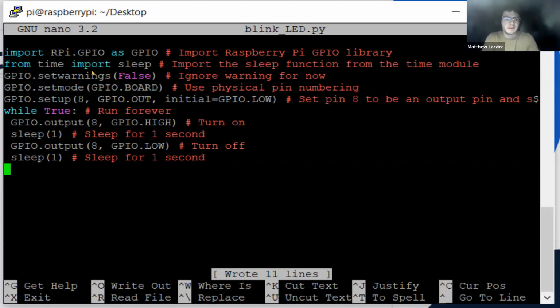But anyway, what I'm doing here is I'm importing the actual package that allows me to work with the GPIO pins. I want the sleep function because I want there to be a break between different blinking sequences. There's also a lot of stuff within the actual package itself that you can set a bunch of specifications about. I'm not super familiar with this, but the point is,